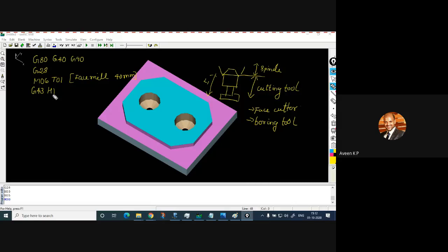Okay, done. So this is done. Then I will lift my tool from origin to the position of 35. Remember, if you want to move your spindle, for example, in this direction, above and below, this will be the Z direction. This direction will be the Y, and this direction will be the X.